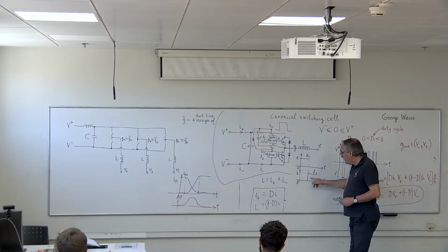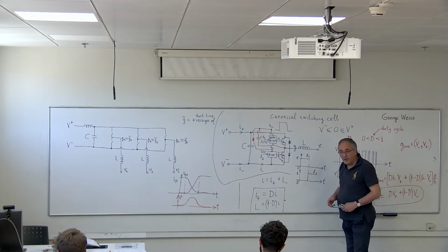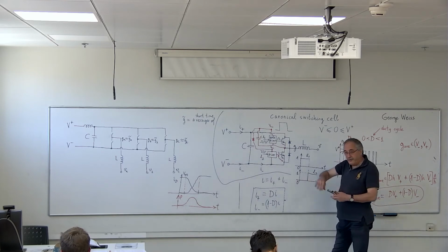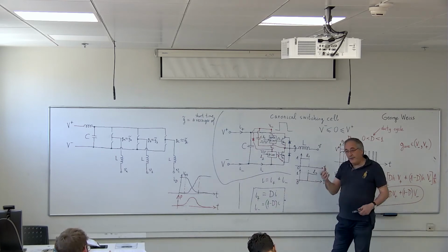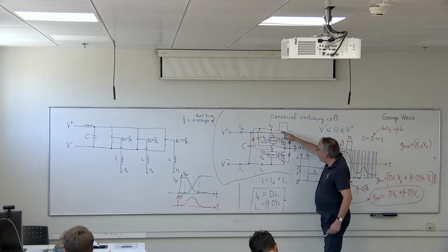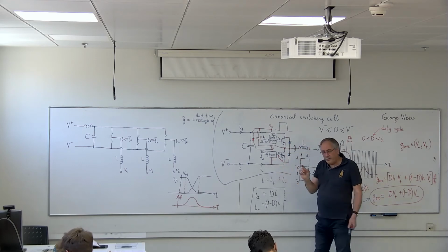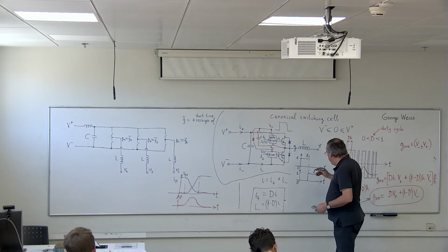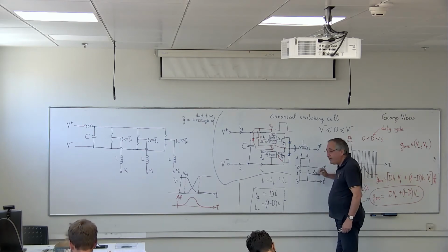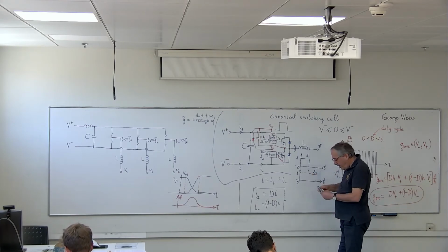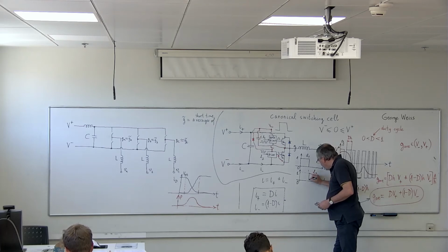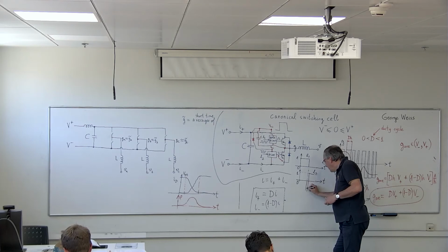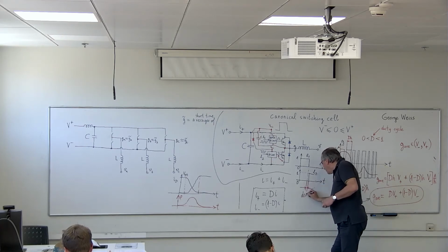Okay. Now, what happens at this moment when one goes down and the other goes up? There will be this transient, which I have shown you here. One will start going down, the other will start going up, which means that during this transient, the current can flow through both switches and create a short circuit. Yes, it's a very short time, but it can happen, and this can destroy the circuit. So how do we prevent this from happening? We have to put a dead time between them. So that means if this signal L1 has stopped being high, then the next signal will go high a little bit later. You see, there is this difference here, which is called dead time.